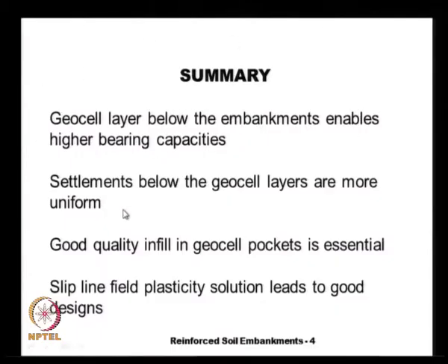and we end up with higher bearing capacities. The settlements that we have below the Geocell reinforced embankments are found to be more uniform, and we need a very good quality infill for the Geocell to be effective. And the slip line field plasticity solutions lead to good designs.